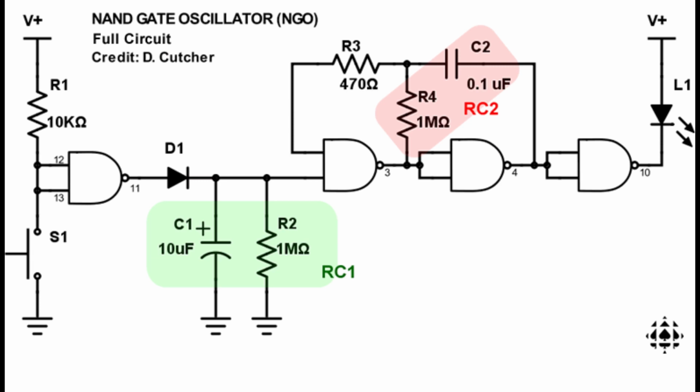This RC uses a large capacitor, anything above 10 microfarads is ideal, that charges up while the button on the input is being pressed. When it charges up, it still allows power to go to the rest of the circuit. Once the button is released, the capacitor expels the charge that it built up, continuing the stream of voltage passing on to the next section of the circuit.